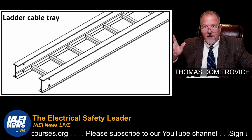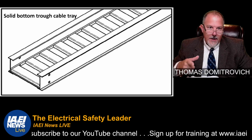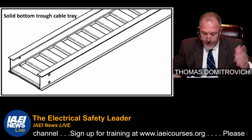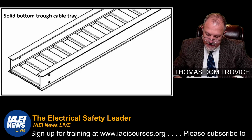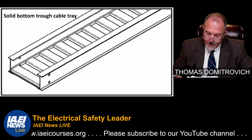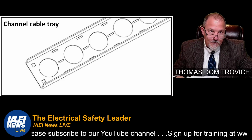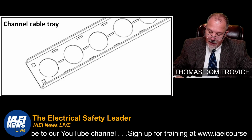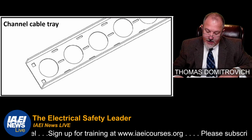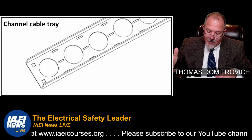So ladder tray, it looks like a ladder, but don't use it as a ladder. Come on. All right, so solid bottom trough cable. This is a solid bottom built like a trough, right? So that's another one that is used. And there's your ladder tray, ventilated channel. So there's your ventilated channel tray. Solid bottom and other similar structures. So they cover a little bit of everything for you in that scope: ladder tray, ventilated trough, ventilated channel, solid bottom, and other similar structures.